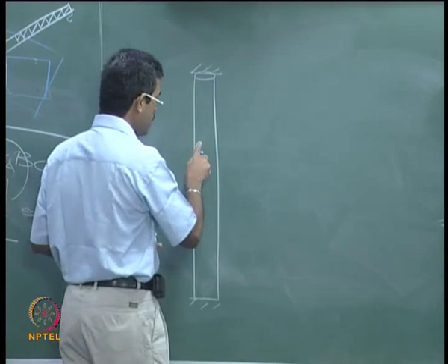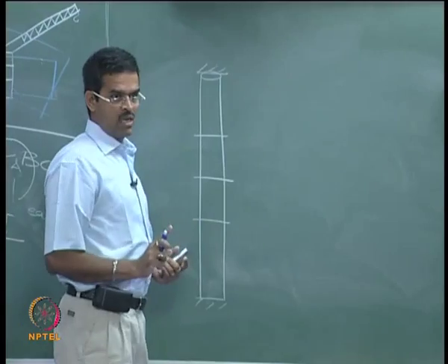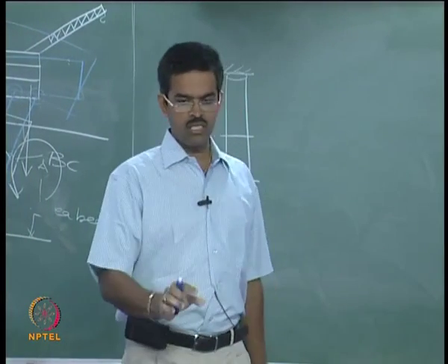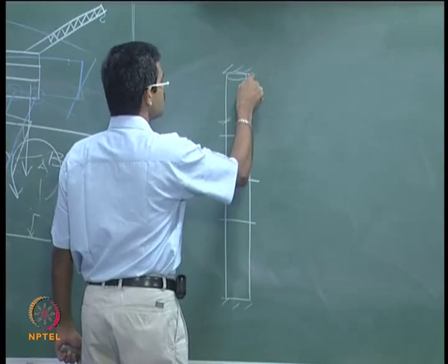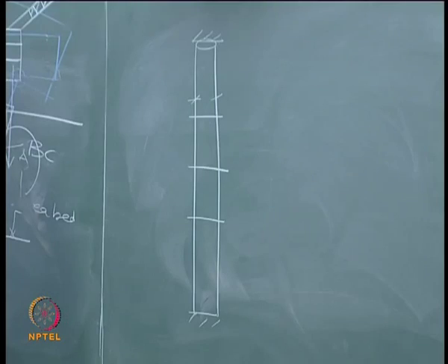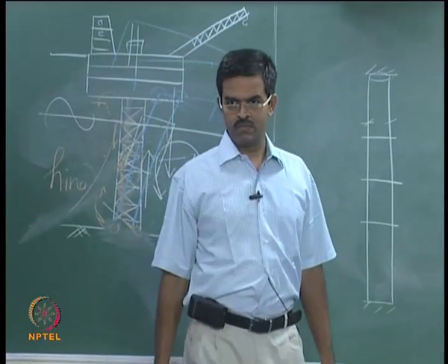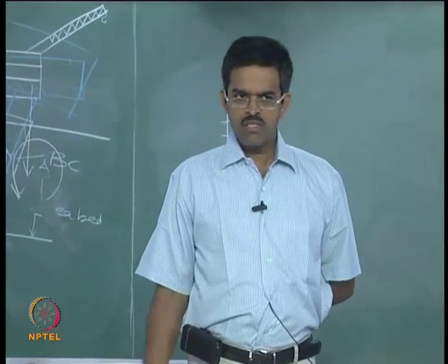I use the same member but put intermediate connections, the member will no more become slender. So, slenderness is a concept, proportionality between the dimension to its supported or unsupported length. Let us not bother about that here. If you worry that my cable will be slender, the cable has to remain slender. You cannot have a stiff cable, but that is not a structural demerit.